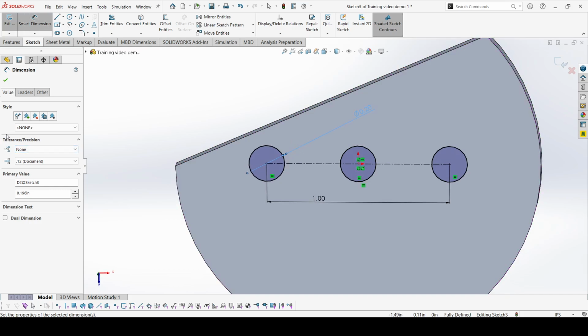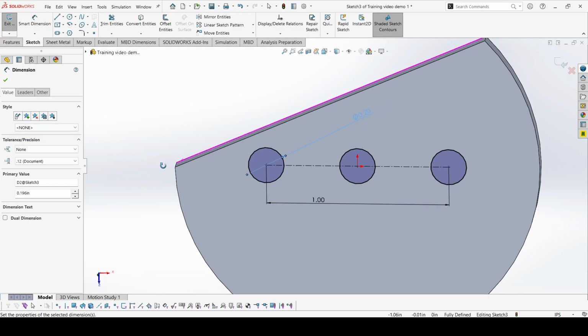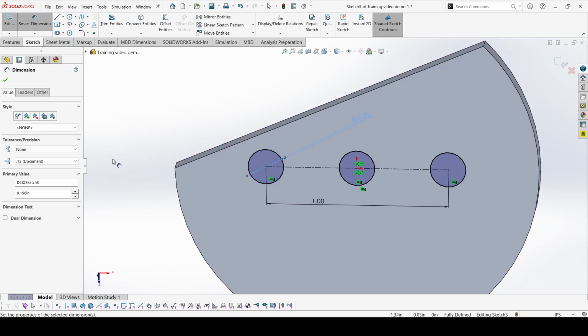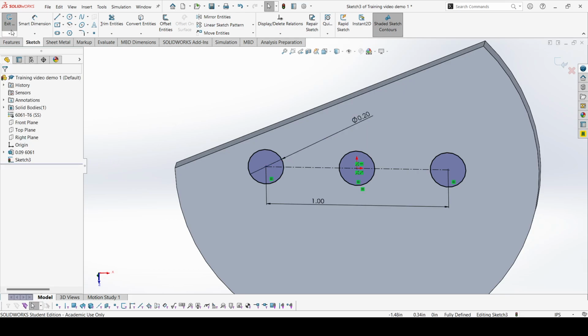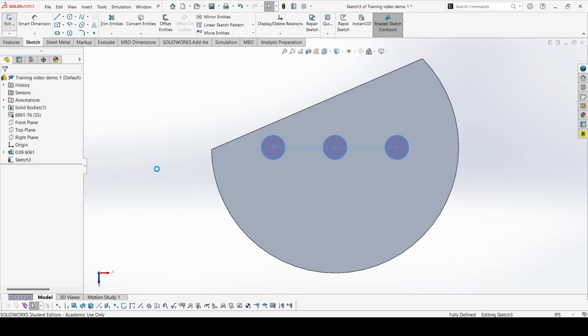This is one of the numbers you will memorize. It is 196. You got 196 holes. This is your 10-32. Rather, just your number 10 hole. The 32 refers to the thread pitch.